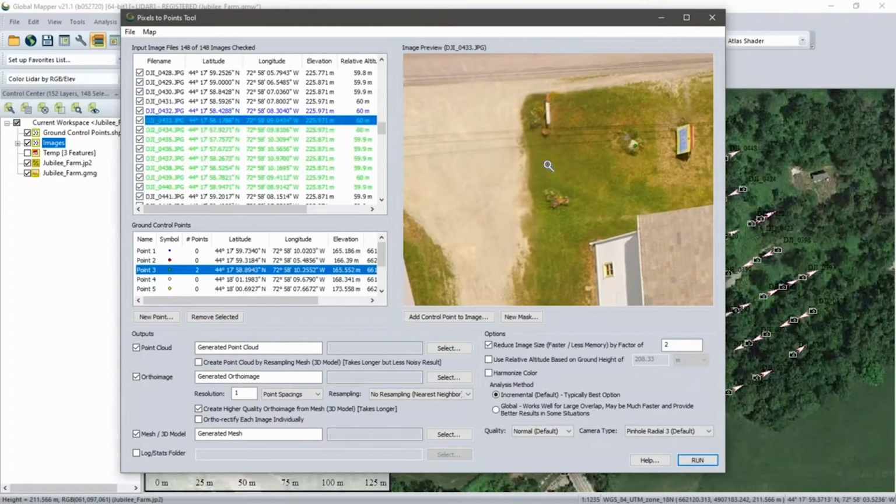And just to clarify, what Mackenzie's tagging is not actually a ground control point. We did identify something in the images to simulate a ground control point. Obviously, before you collect the images, before you send your drone up, you would have identified placement of a target or something of that type. That would be the basis of your ground control. We're just pretending that this was a ground control point in this case.